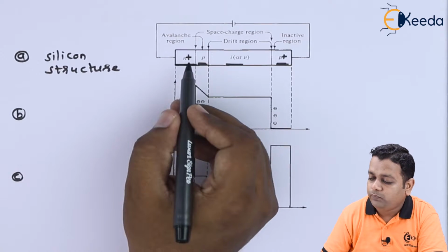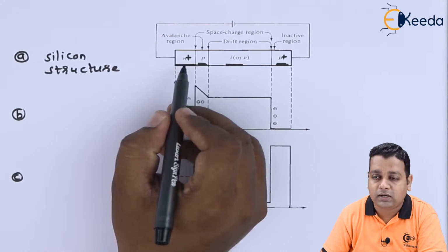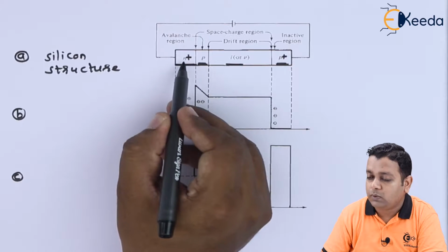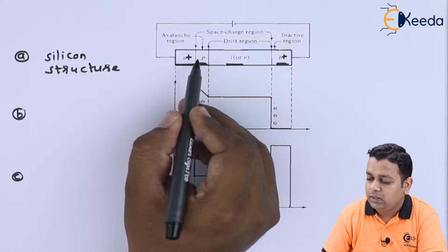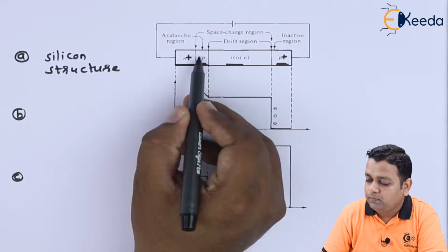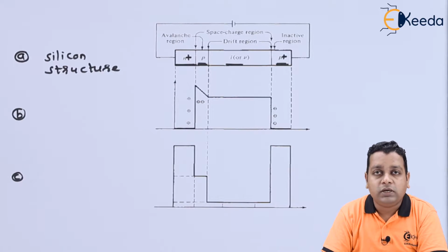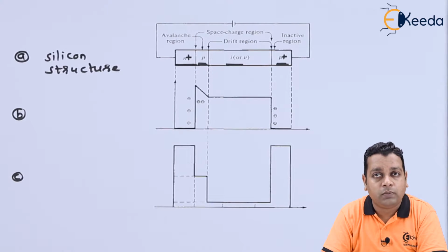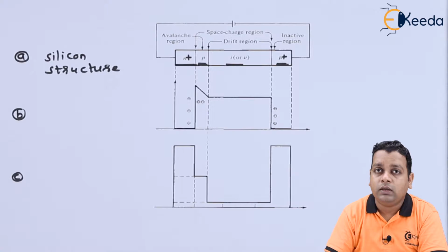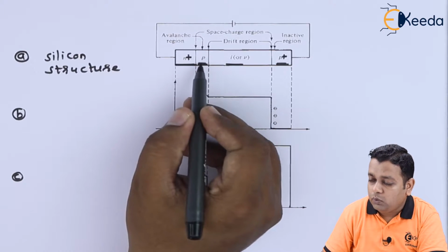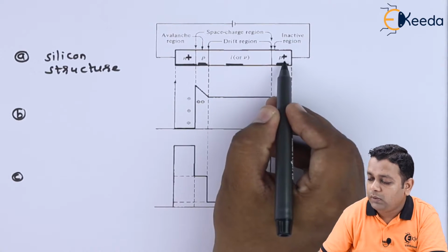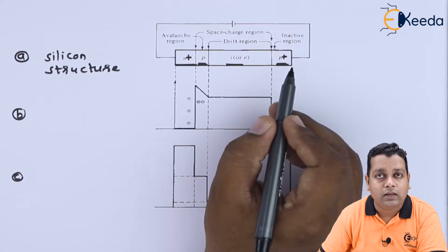As we start from the left-hand side, we come across the first junction between the N plus and the P. In this P region, the avalanche multiplication, or avalanche effect, starts, and we can say there is formation of a high field domain, and that high field domain must drift from this location up to the P plus region at the right-hand extreme.